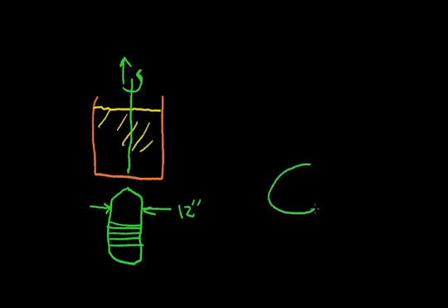So let's draw one of these little slices over here. And we'll call this a wafer, or a silicon wafer. And what we can do is manufacture many hundreds or thousands of chips on this wafer. They're all manufactured together at the same time. For example, one of these squares may be a chip. And these chips can contain millions, even billions of electrical components, or transistors. Now, these transistors, or these components, are made by changing the regions within this chip, by changing regions to P-type and regions to N-type. These electrical components can be manufactured.